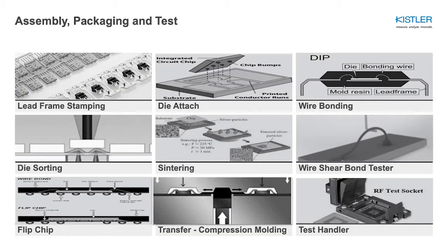Lead frame stamping, die attach and wire bonding are traditional applications and have been supported by Kistler for decades. However, here as well, miniaturization and higher quality requirements are demanding better process control, and dynamic force control can add value. The types of wire bonder, like thermocompression, thermosonic, and ultrasonic, can all be supported with piezo dynamic force measurement.